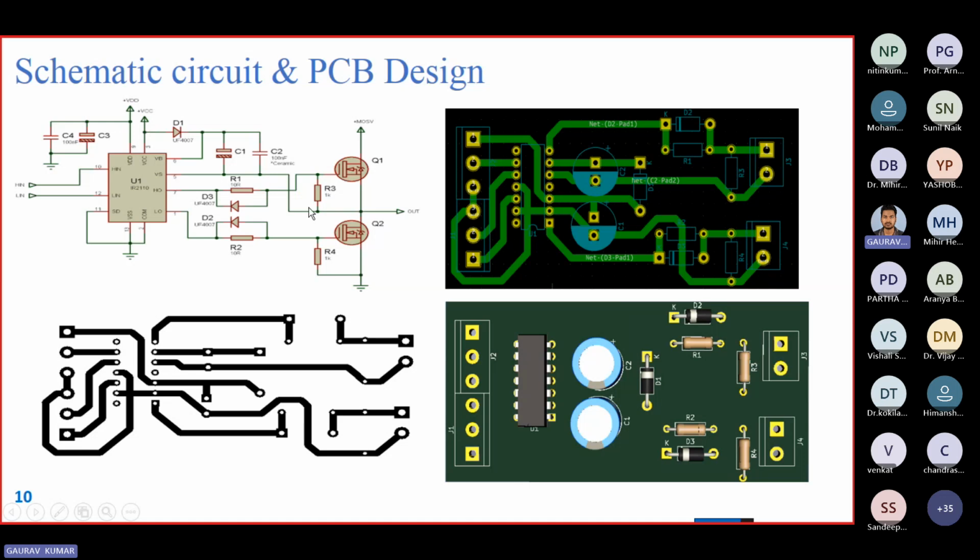Okay. And when we try to turn on the Q1, then in the next half cycle, when it is fully charged, the bootstrap diode becomes reverse biased, and this capacitance discharges through this path R1, and through the HO, and it will go to the Q1 output, and it will turn on the MOSFET. Okay. So this is the schematic circuit of the IR2110.